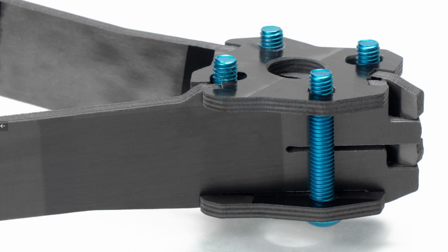Yeah, we believe it has a resonance frequency slightly over 800 hertz. It depends a little bit on your motor weight and prop weight and so on. I've seen logs with 860 hertz, some with 810 hertz of resonance frequency. So it's really high, because normally frames have around 200, 250 maybe. And the maximum speed of a motor is 450, 500, something like that. So ideally, I want to push it over 1,000.